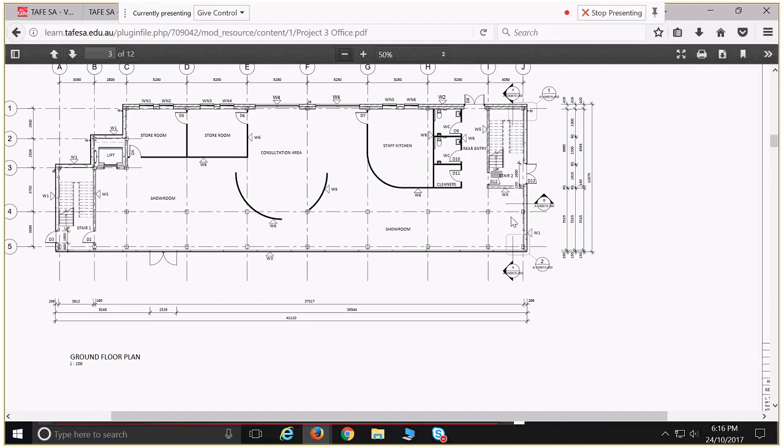Now, what I could then do with this is take away this building, and if we want to do a footings plan, we know that the center point of our footings to support this column at D5 is at that dimension of D5. So it makes the structural elements easily transferable between the floor levels. Does that make sense as to what that's used for?